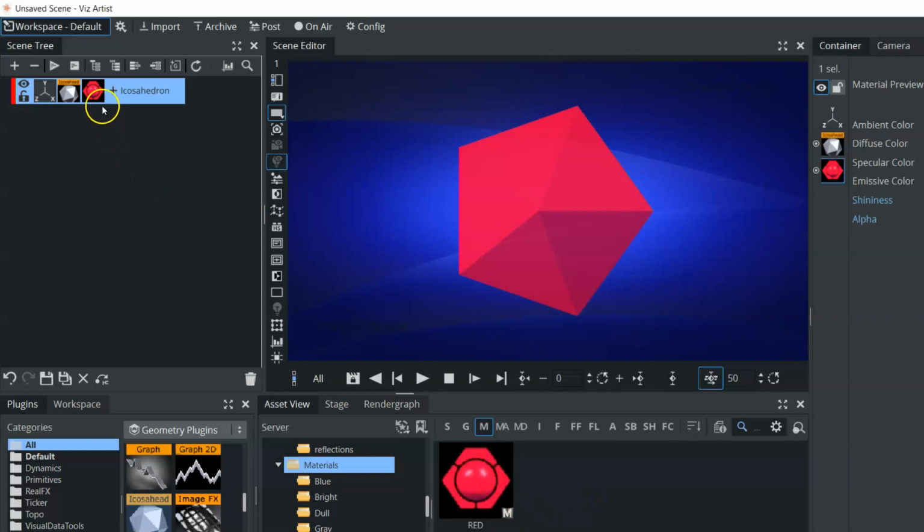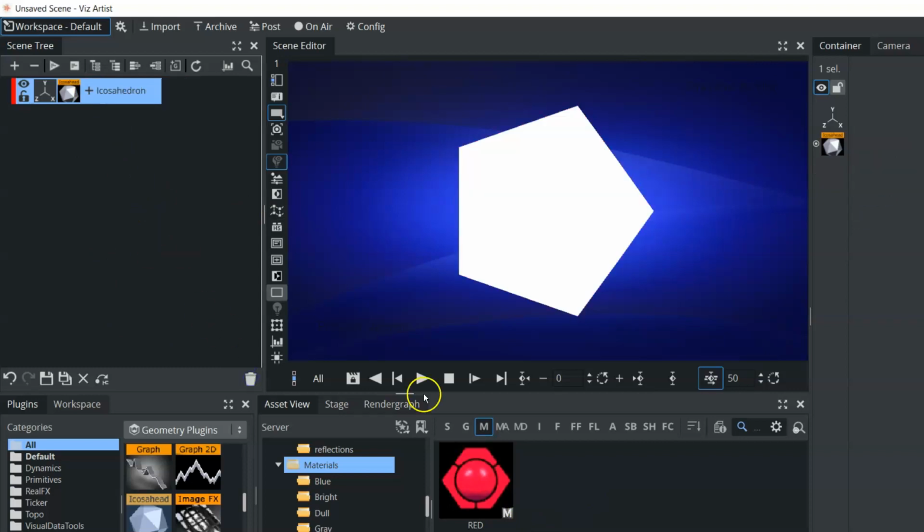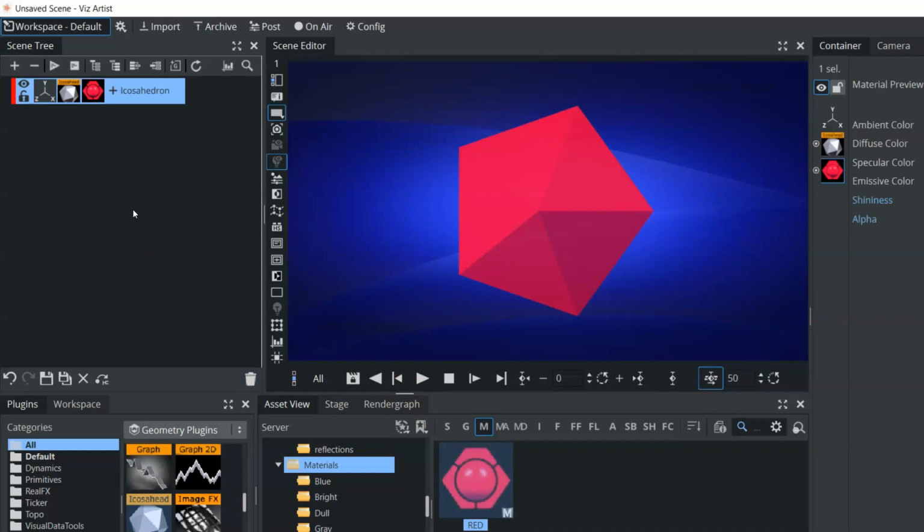If you want to get rid of the color on the container, you simply drag that to the trash can. We can drag that material back on. If you want a flat color, then there's a little icon next to the properties window in this column here. You can simply turn that off, and now it creates a flat color and shows you no depth on that 3D object.